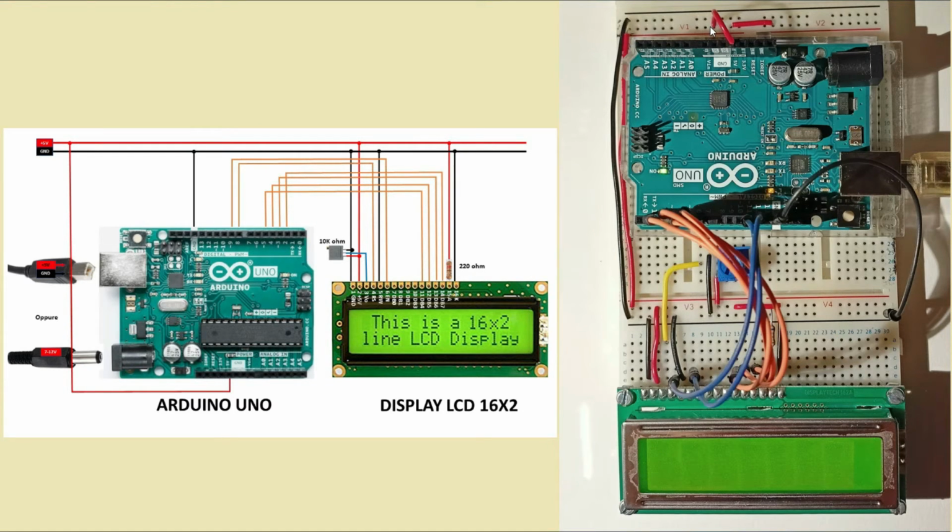So I connected the 5V here to the 5V pin on the Arduino Uno, and then I brought the ground connections to pin 1, then to the 5V, which we see over here, and finally to the last pin, which is 16V. All of these jumpers connect to the ground of the Arduino board through this jumper here, which goes to the GND pin of the Arduino board.